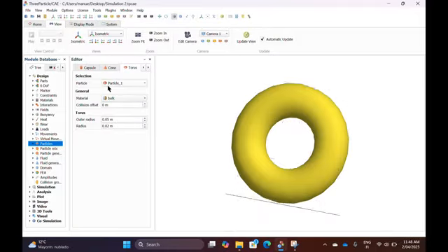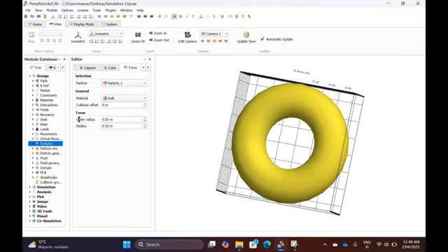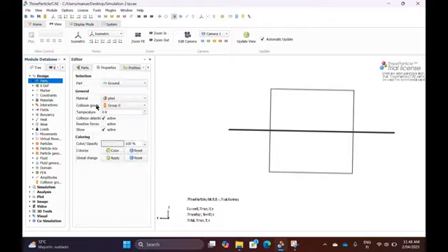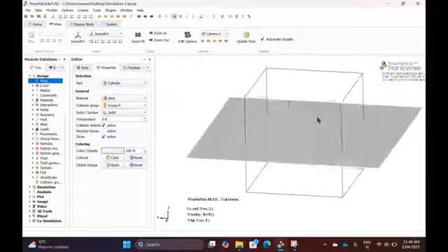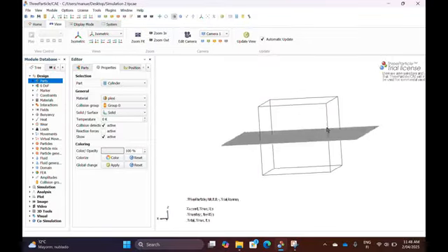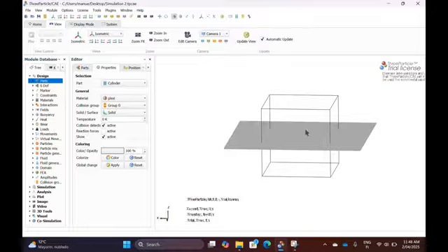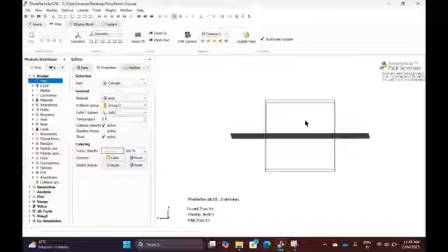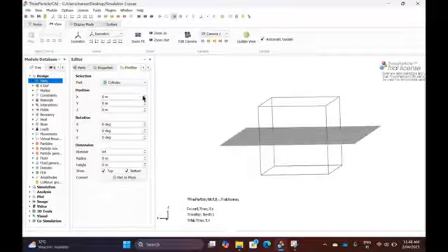After that, I directly switch to parts. I define the ground as a plane, and we put here ground. And then I define a cylinder and call that one cylinder. Very quick. But the cylinder is not defined yet in its size. So we have the ground with 1 meter times 1 meter, that is default. But you can't see the cylinder because when you go to position, a cylinder has no radius and no height yet. So if I increase that a little, I can already see it a little.